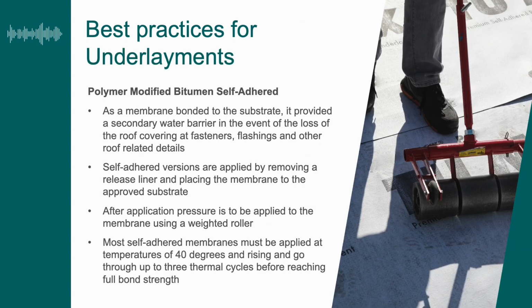So the other category of underlayments are your self-adhered, and specifically the polymer-modified bitumen self-adhered underlayment, which has an asphalt compound that provides the waterproofing. These types of underlayments are bonded directly to the substrate, which is typically going to be your plywood deck, and it provides a true secondary water barrier in the event of the loss of roof covering or at fasteners or flashings or other critical areas.